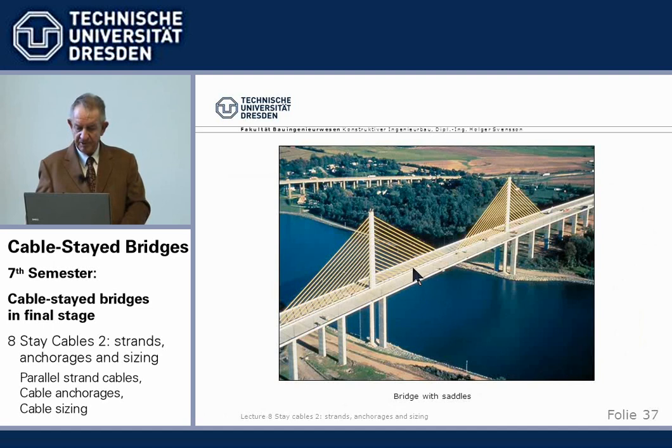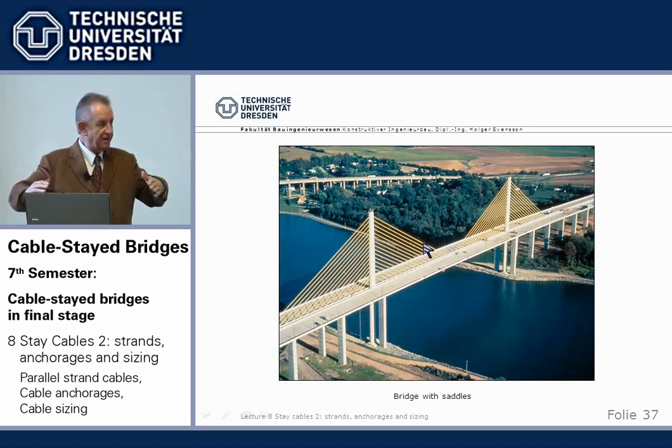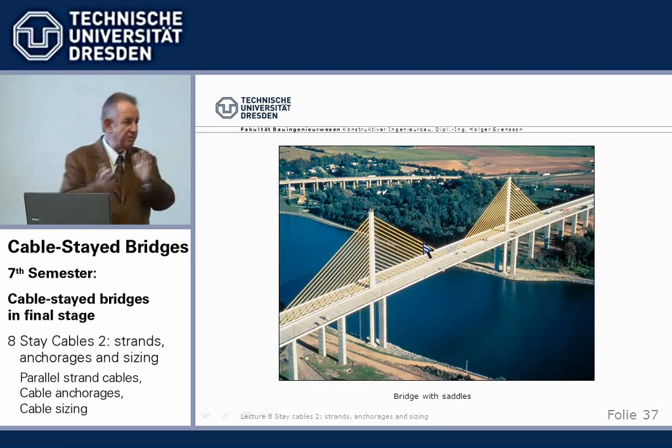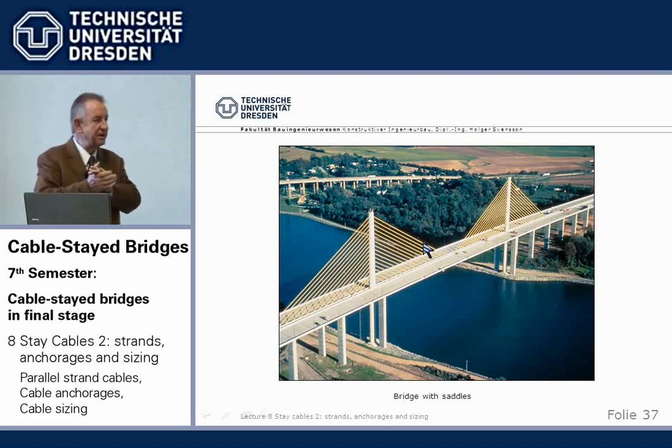If we have a track load standing here, then the force is transferred by the cable up here, and a large part of it goes up then to the backstay cable into here. Which means this part of the cable is under live load stress, and this basically has no live load stress, roughly speaking. Okay, so we have a difference between left and right in the cable, up to 30–40% of the cable capacity. And that the cable must not slip through, must not slide.